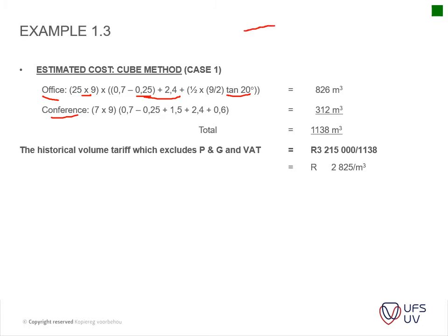If we've got our natural ground level here, and then we've got our strip footing, which is here, basically what you want is this height here. You just subtract that 250 mil, which is here. Okay, that's all that's happening on this side. Then you add the top of your ceiling heights, and then what you need to calculate now is the middle of your roof height.